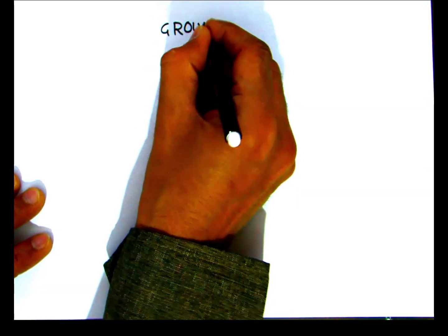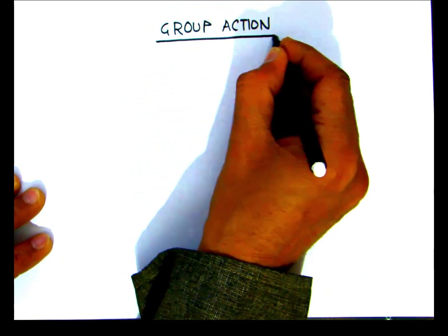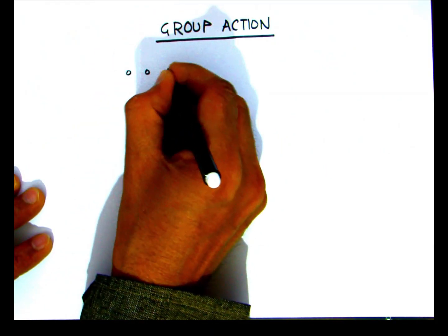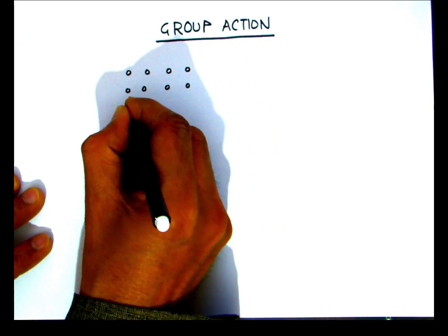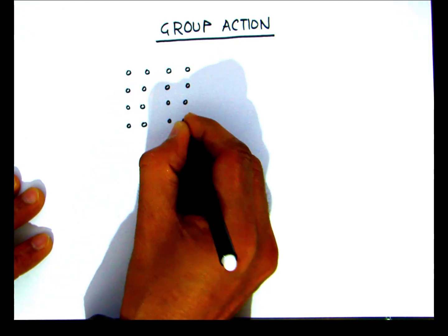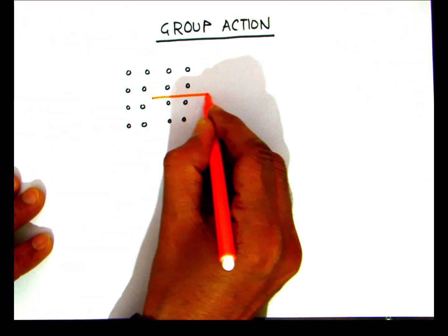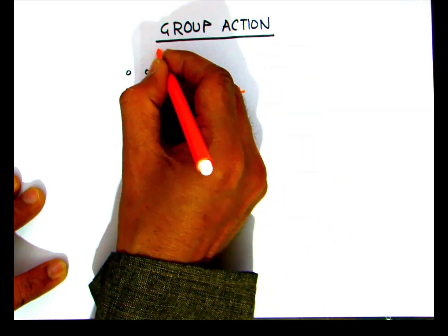After having learned the expressions for the vertical and the horizontal stiffness of a single pile, we can very easily obtain the values for groups of piles, because usually we have groups of piles supporting a machine foundation. Here the analogy is just like the case of the elastic pads, and essentially we follow the computation which is usually used in the case of steel structures for groups of rivets.